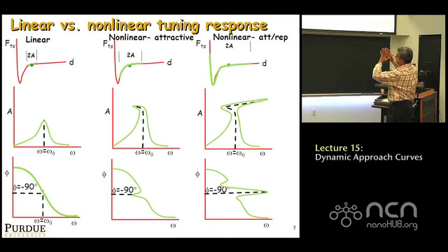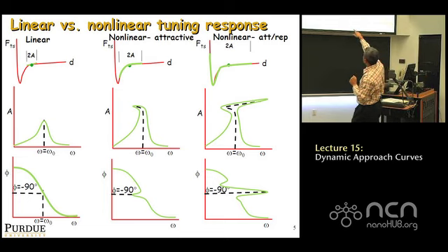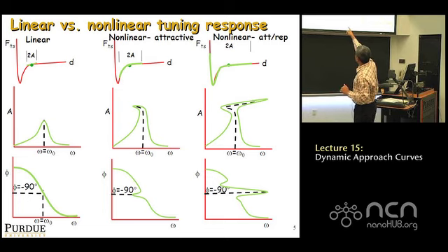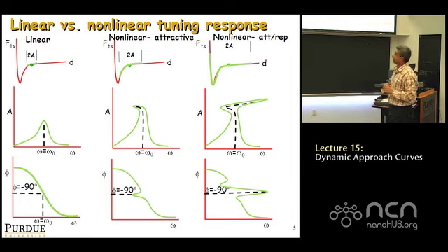What the resonance peak does is it tips a little to the left. So it becomes asymmetric. It does this, okay? And if you think about the dashed line, it suggests that there is sort of a backbone to this peak that curves a little bit. It goes up and curves. Whereas in the linearized response, that backbone is simply a straight line. This curve pretty much is symmetric about that one line. Whereas in this case, you've got a backbone that curves like a hockey stick, right?